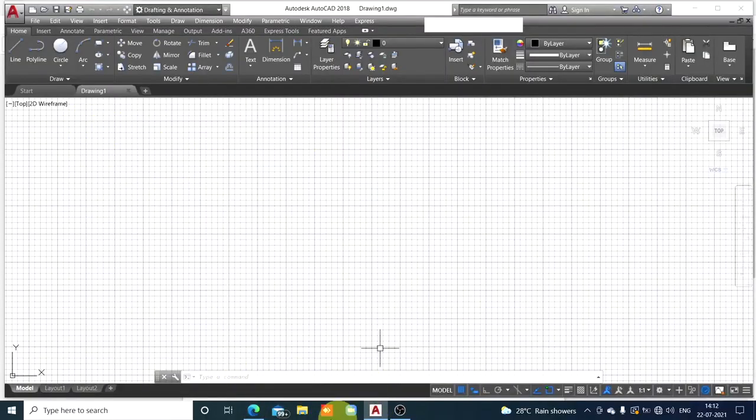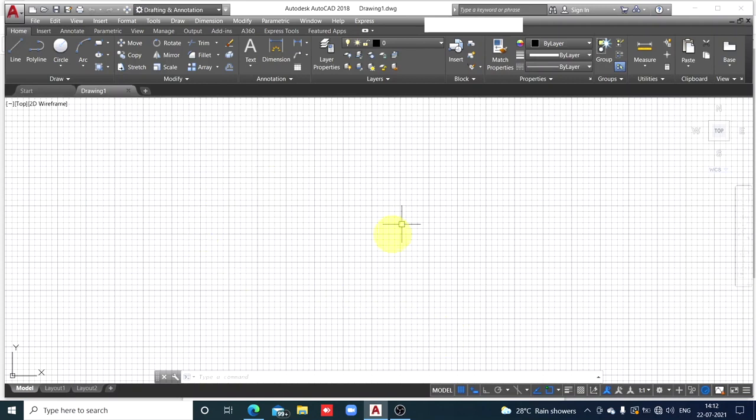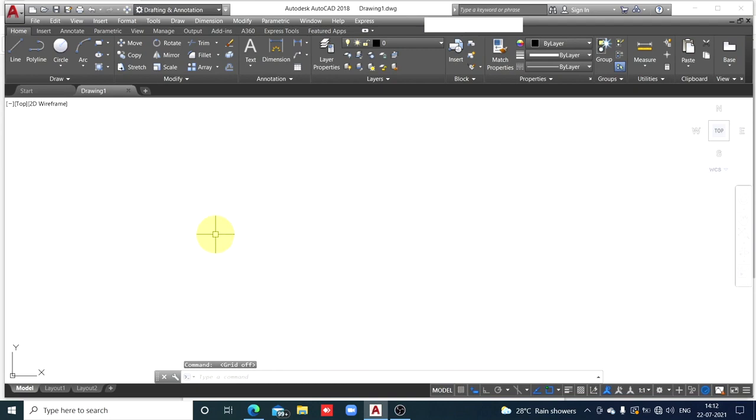So here we have opened AutoCAD, new drawing, drawing 1, and here we are going to draw that isometric view. I don't prefer this grid, so I'll make this grid toggle key off. We want these 4 keys on, as I told you, basically. Dynamic input on, blue colored means it is on, ortho mode on, then snapping reference lines on, and snap cursor to 2D reference points on.